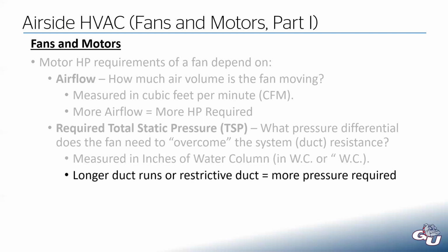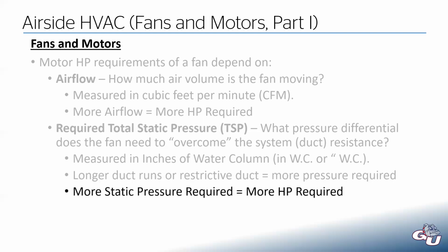And if you have longer duct runs, or if your duct is restrictive, meaning what if your ductwork is undersized for the amount of air you're moving? Well, that means it's going to be moving faster, which means there's going to be more friction. So if you have longer runs, or more restrictive duct runs, that's going to require more pressure from your fan, and the more pressure output from the fan you need, the more horsepower you're going to need.